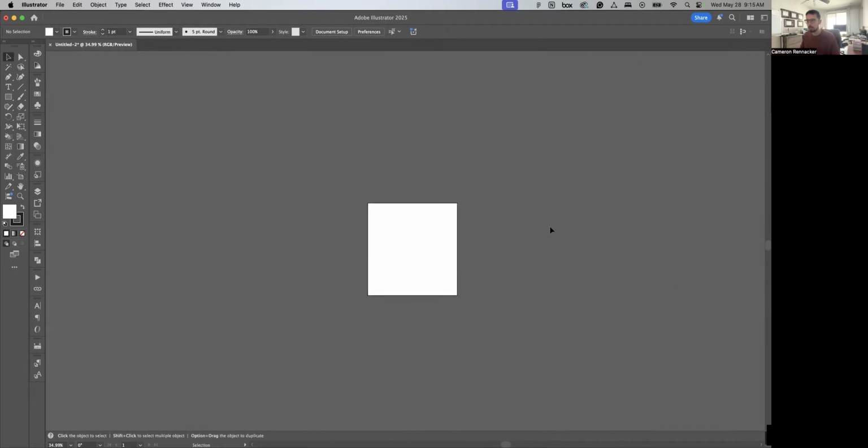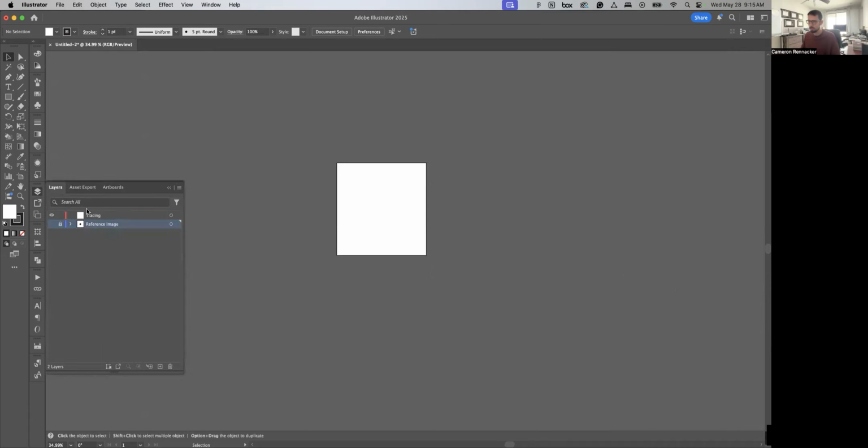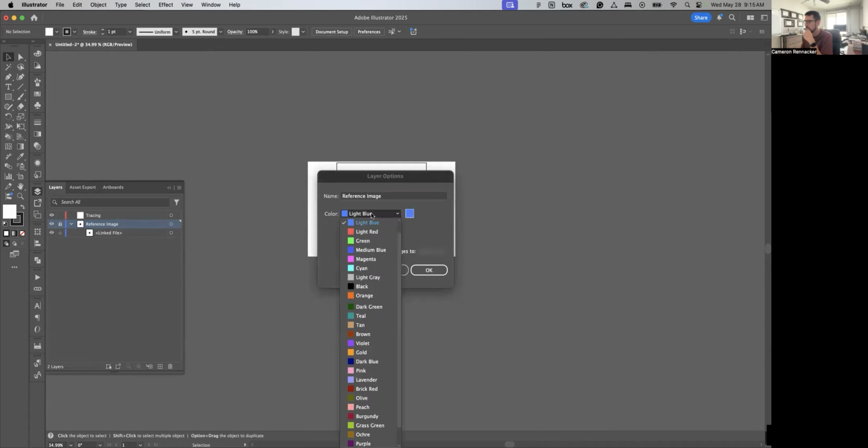Now, from there, let's talk about layers. We've already sort of seen ourselves working with that. You can turn layers on and off. You can lock them and unlock them. You can change the name of them. You can expand these layers to see what's inside of them. I'll come back to that in a little bit. You can even double click and you can change the color that that layer is specified as. You can make it a template, which you probably won't really need a whole lot of. You can show or hide it, preview or not preview it.